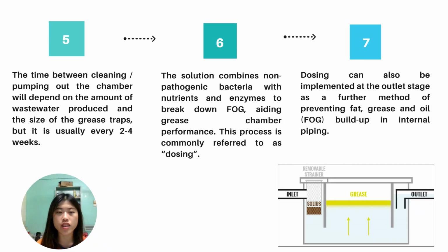actually, the time between cleaning or pumping out the chamber will depend on the amount of wastewater produced and the size of the grease trap, but it's usually every 2 to 4 weeks.